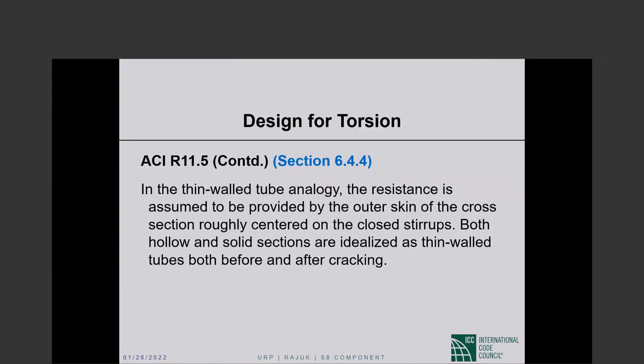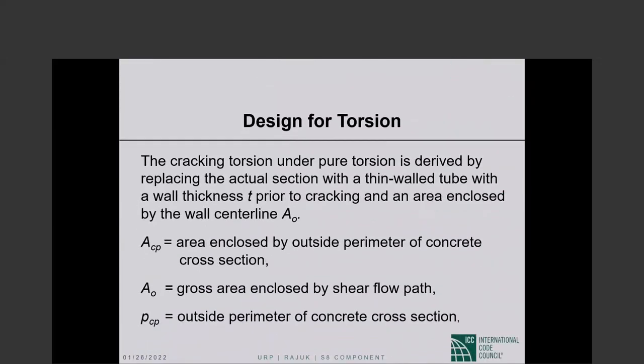Both hollow and solid sections are idealized as thin-walled tubes both before and after cracking. So a solid section will also be treated as a thin-wall tube for the purpose of torsion design.